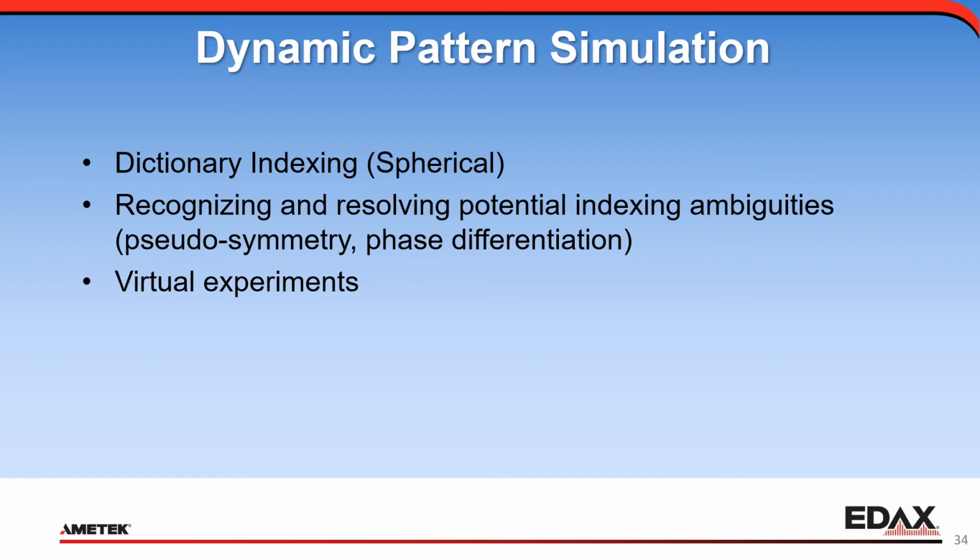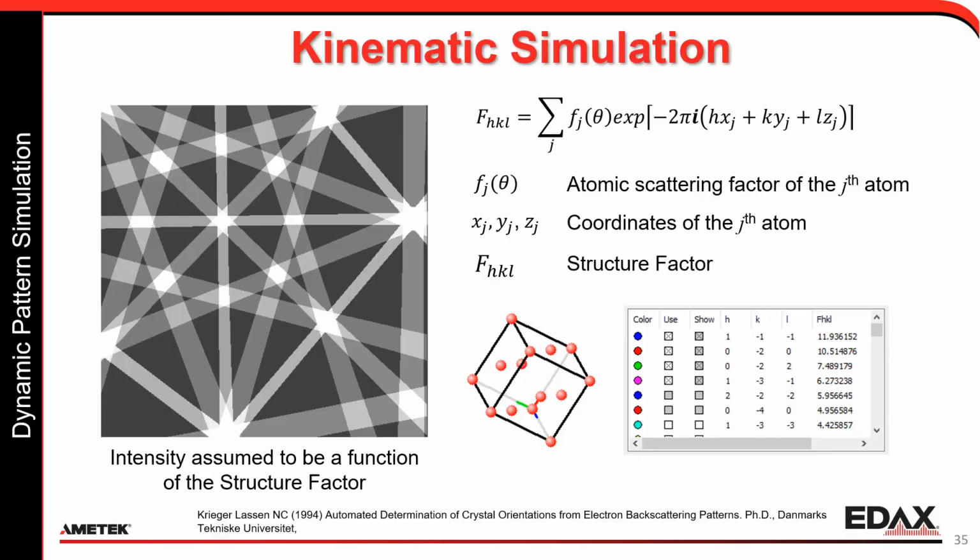Another big area that I see a great future in, and we're already seeing, is dynamic pattern simulation. Let me show you some of the ideas that are already there, and that are increasing in both application and in advancing the techniques. We started out with kinematic simulation to understand our EBSD patterns, to understand which reflectors we expect to find, and that helped us in our Hough indexing.